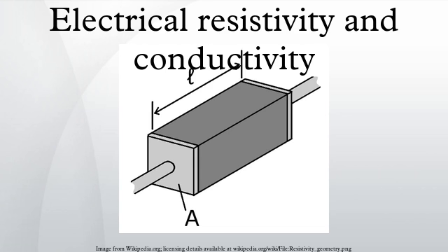In a hydraulic analogy, passing current through a high resistivity material is like pushing water through a pipe full of sand, while passing current through a low resistivity material is like pushing water through an empty pipe. If the pipes are the same size and shape, the pipe full of sand has higher resistance to flow. But resistance is not solely determined by the presence or absence of sand. It also depends on the length and width of the pipe. Short or wide pipes will have lower resistance than narrow or long pipes.